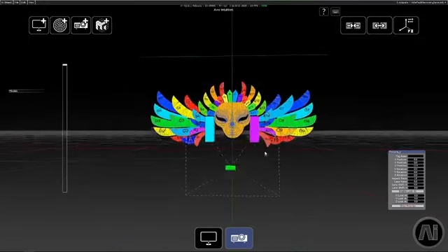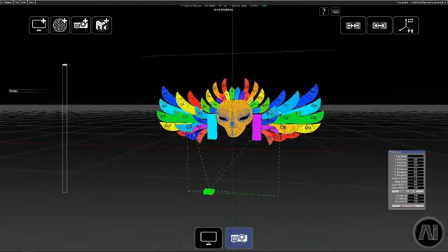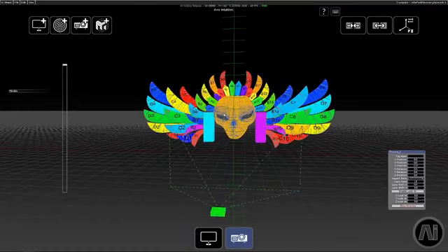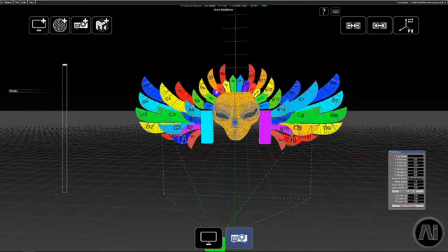My projector at the moment has a square cone, so we need to get that into something more standard. So I'm going to go for a 16:9 ratio. On the projectors you can put into the lens ratio the sum 16 divided by 9 and it will give you the correct value, which is really handy. In fact, I should have put an aspect ratio and not lens ratio. Let's go for that, and I'm going to give myself quite a low lens ratio just for now.